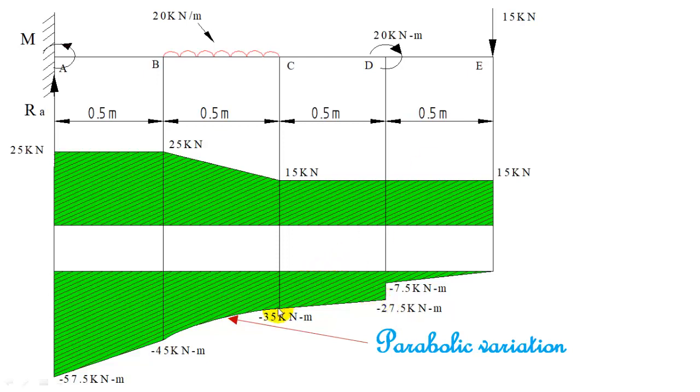Don't directly join from minus 35 to minus 7.5, because right of D is minus 7.5. So you have to join to left of D, minus 35 to minus 27.5, and right of D it is minus 7.5. So that change will happen at that point D, minus 27.5 to minus 7.5. That is the effect of the couple. A couple will suddenly change the bending moment at that point.